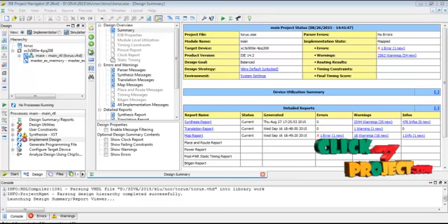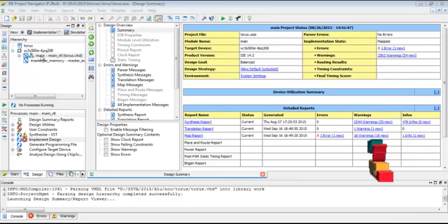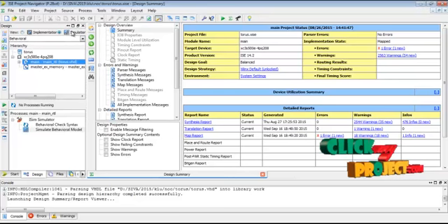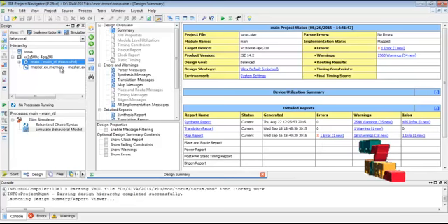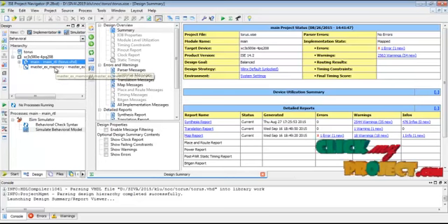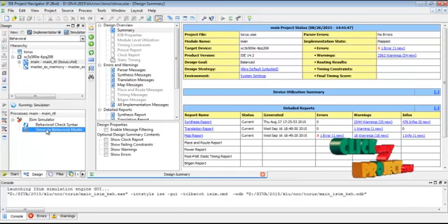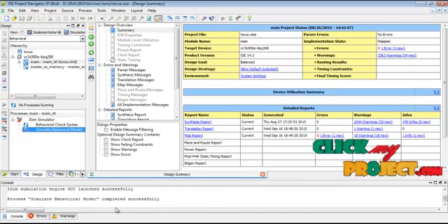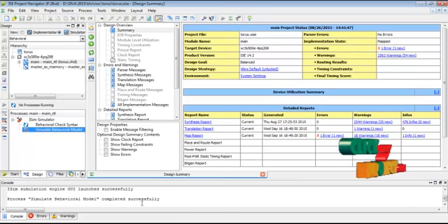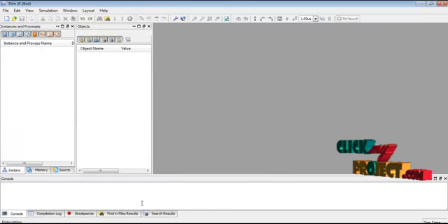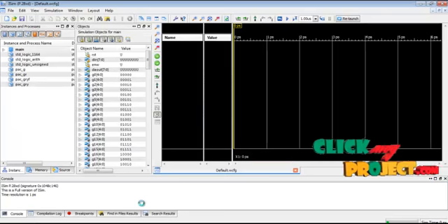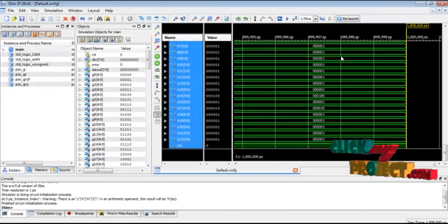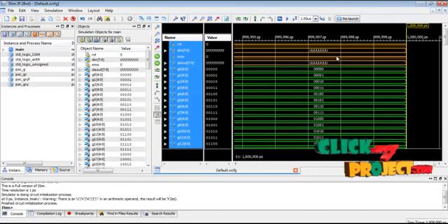Our process was done in Xilinx 14.2 software. This is our program for the overall 3D based NoC architecture design. This is our simulation process. Then we select the simulation, select simulate behavioral model, and double click the simulate behavioral model section. After the behavioral model completes successfully, the iSim project navigator is created. This navigator is used to simulate the overall processing level. This is our simulation window for our required input output architecture designs.